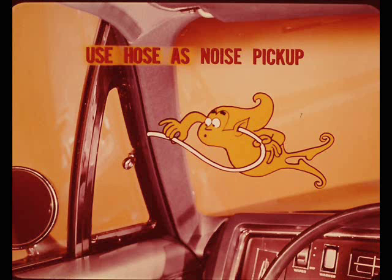That about wraps up air leaks, Al. How about turbulence noises? Well, we've already talked about loose moldings and body joint gaps or openings. If everything appears shipshape, you can close off or cover other suspected areas with masking tape and make additional test runs to check the effect.